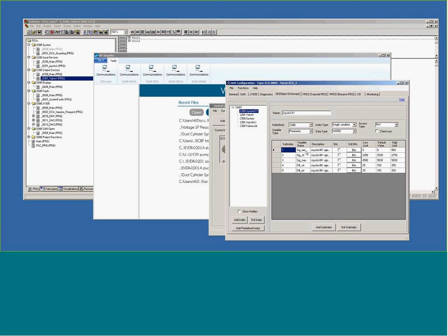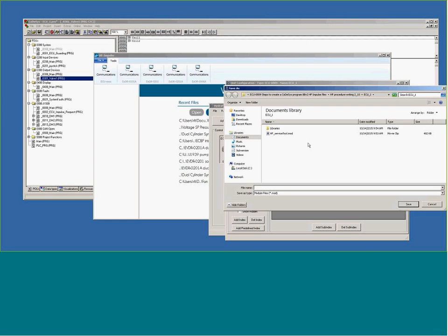Again, joystick 1 signal minimum, signal center, signal max, deadband center, deadband error, tuning for both coil 1 and 2, current minimum, current maximum. The system looking at system voltage, 5-volt reference, internal temp variables. Then in RAM, I wanted to monitor what was going on with the joystick in millivolts, and I want to monitor what's going on with current on both the coils. I'd taken this and we had done a save configuration and a MOD file that I called HF service mod.